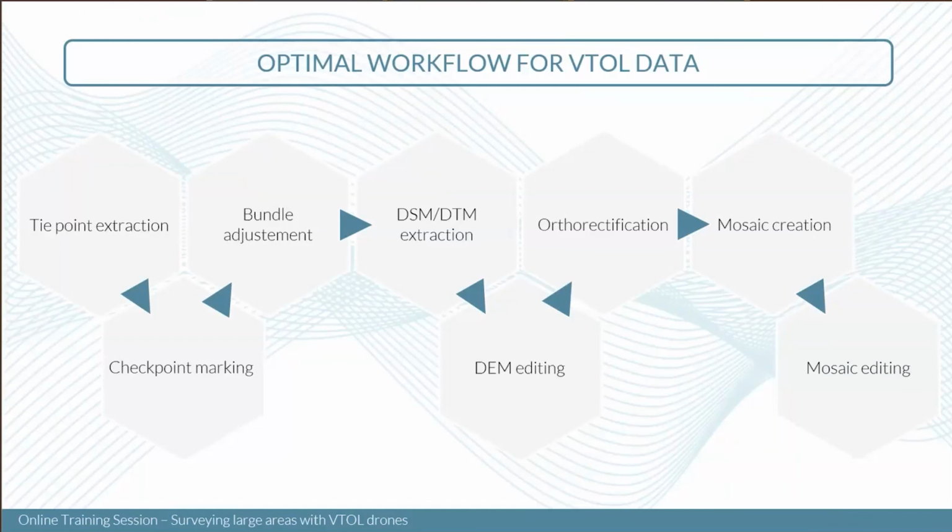Once your elevation data is good regarding your needs, you'll be able to perform the ortho rectification of all the images of your flight and then generate a seamless mosaic with all the ortho photos at the end. And you'll also be able to edit or to play with the radiometric values of your mosaic and also play with the seam lines of your mosaic if you want to refine the visual aspects of the results.